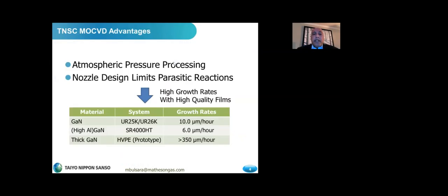TNSC MOCVD systems have several advantages. I highlight two here: atmospheric pressure processing and an injection nozzle design that limits parasitic reactions. These combined allow for the high growth rate of high quality films.